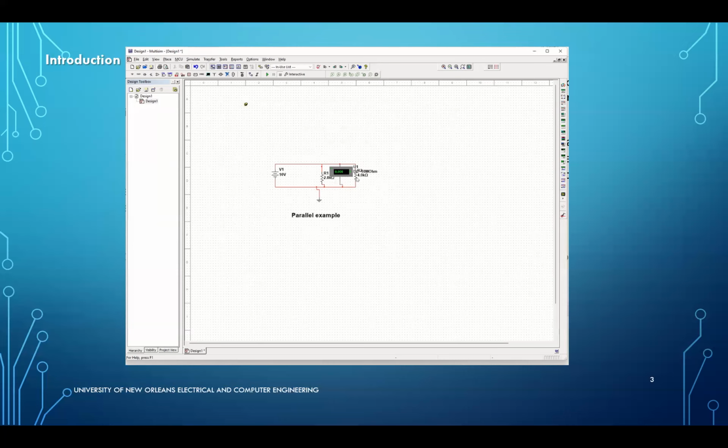And now I'm measuring right across. Obviously, that kind of obfuscated the information about R2, but I can move it. If I select it, I can move R2 as far as I want, so I still have information. I can move the meter again, move R2 again to give it more room, and so forth. So you can see now I have a connection for my voltmeter like that, and it's going to measure the voltage across R1 and R2, which I already know is 10 volts.